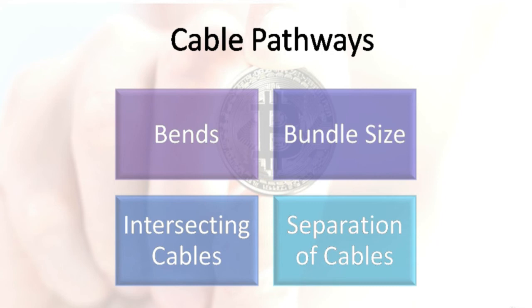Now, with bends, when designing the pathway or routes for your cables, you need to make sure that none of the bends are less than the bending radius set by the manufacturer. And if the bends are too tight, the cable may become damaged. As for the bundle size, there is no limit as to how many cables you can bundle at the same time, but do keep in mind that the bigger the cable bundle, the harder it is to manage and maneuver. So put that in the back of your mind when imagining you're pulling cables. The higher the number of cables in your bundle, the harder it is to pull.